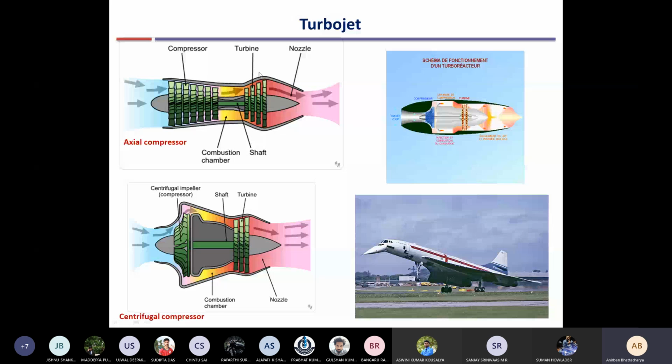and the rest of the fluid still has quite a bit of enthalpy. It is not reduced to very low temperature and pressure. The pressure remains still high as compared to atmospheric pressure. So then there is a pressure drop in the nozzle up to the atmospheric, and you get accelerated flow outside. The ultimate aim was to just generate thrust, which means that the flow has to be accelerated outside. Now we can use a rocket to accelerate the flow to the outside, or a jet engine. So in this case, we are using air breathing jet engines, gas turbines, to accelerate the flow to the outside. Okay, so that is the thing.